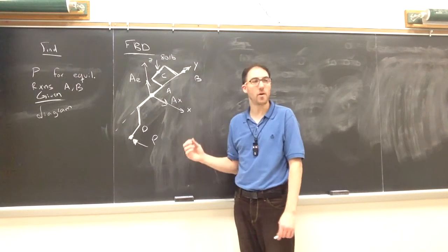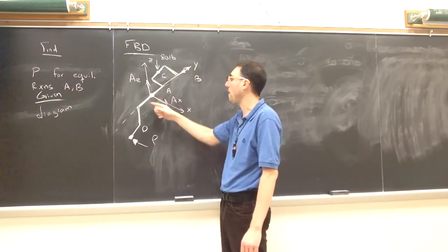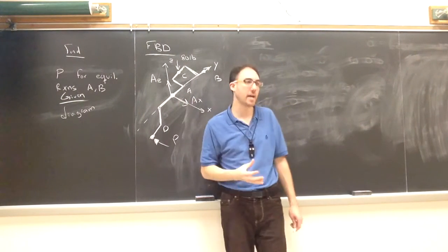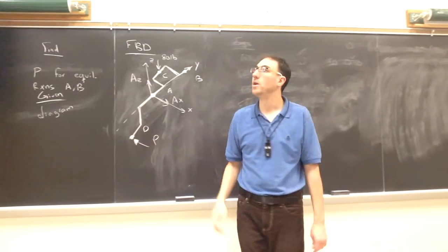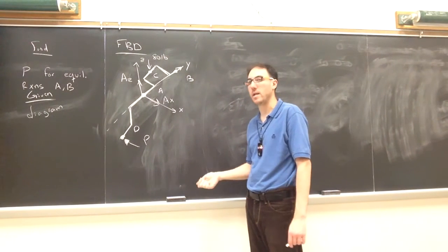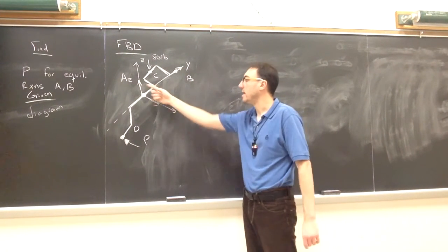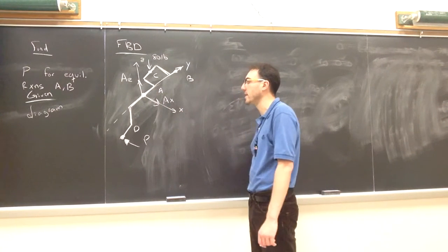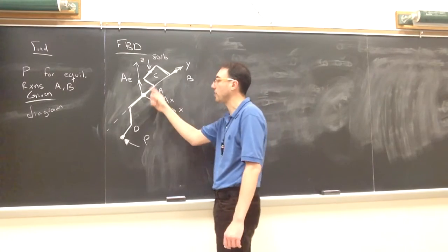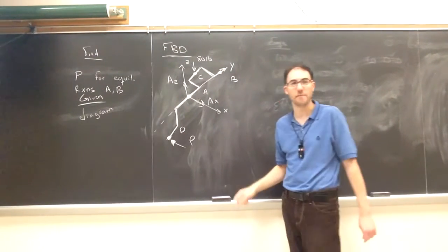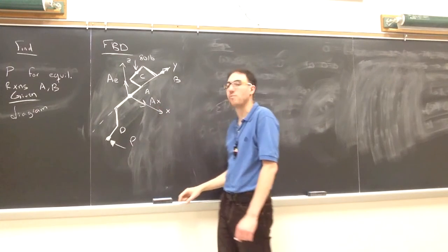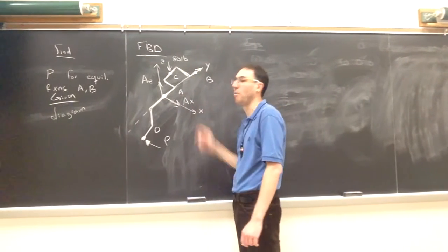They tell us that the two bearings are properly aligned, so the bearing does not exert any couples onto the shaft. So for the journal bearing that is properly aligned, or self-aligned, we just have a force component in the x and a force component in the z, the two orthogonal directions to the longitudinal axis of the shaft. For point A, those are the only two reactions acting.